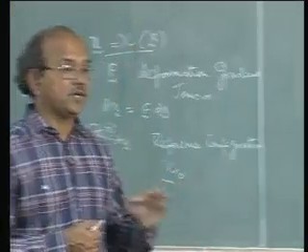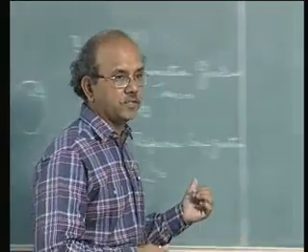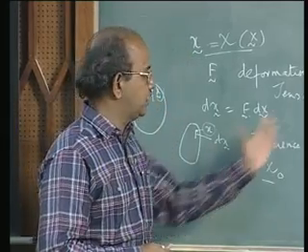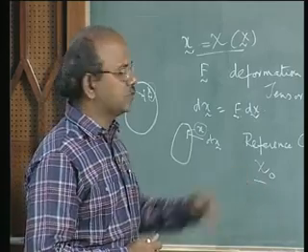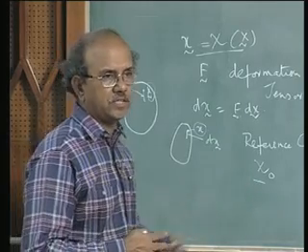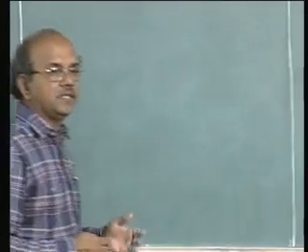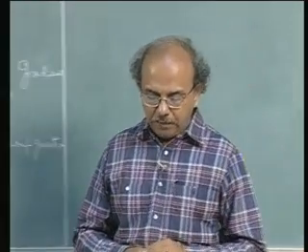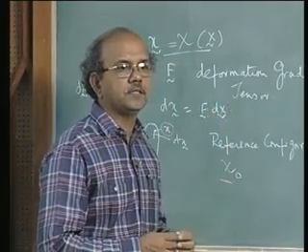So it is not necessary that the reference configuration should be reached at any time of interest to us, but you should understand that we need a reference configuration from which we would proceed for further analysis. But fortunately for us, most of the time the reference configuration is defined very neatly for engineering structures, and it happens to be the configuration at t equal to 0. So with that in mind, let us proceed. Of course, we have defined F to be a two-point tensor and so on.